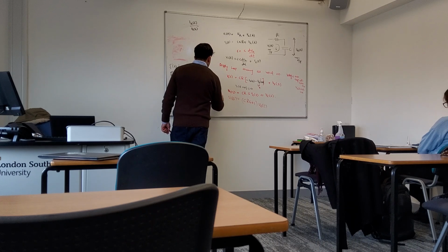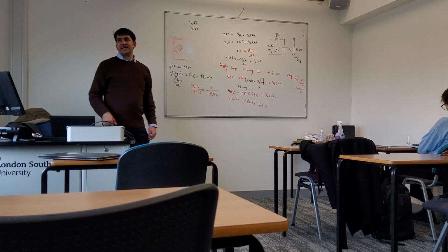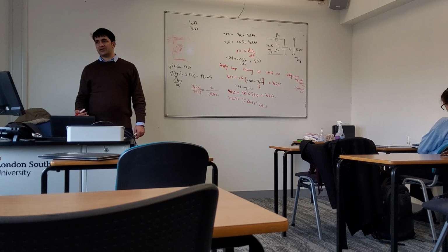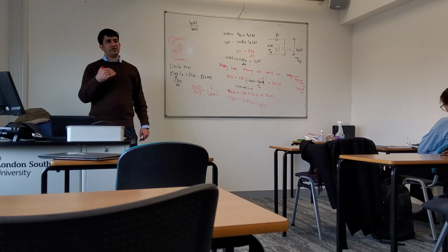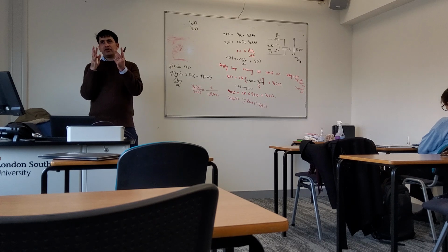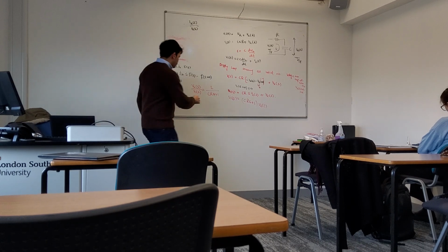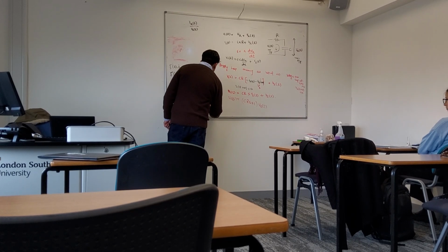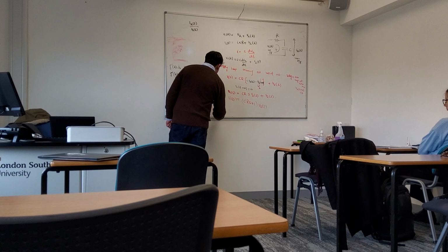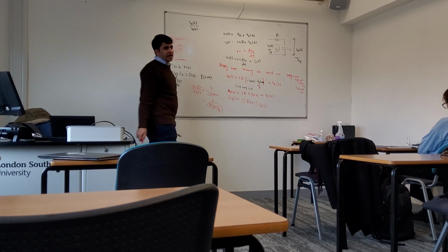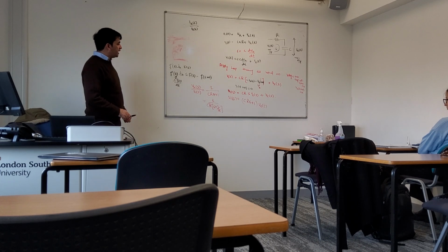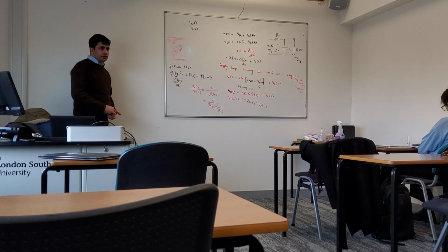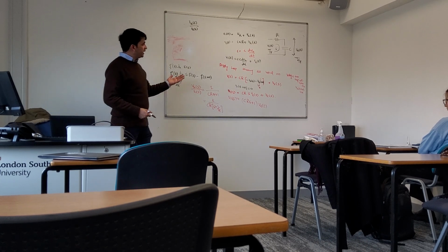So it would be 1 divided by (CRs plus 1). And normally, whenever we write a Laplace transform, we also go back to the time domain, so it's always important to make your function look like a known transform. So I can write it as 1 divided by CR times (s plus 1 over RC). This is what I can do, okay?